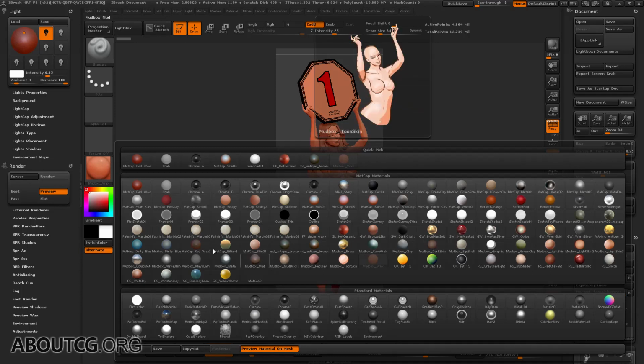It won't be changed by the light you cast. If you want to render a model with light source information, then I suggest you use this standard material ball in the lower section. Of course, we can also use both of these material spheres for rendering simultaneously, and finally composite in Photoshop to achieve the effect we need.